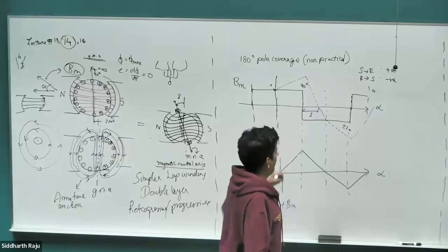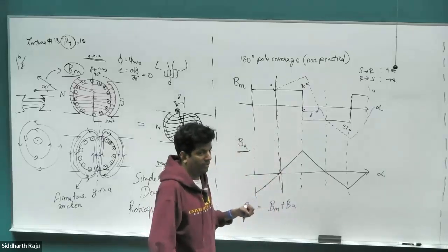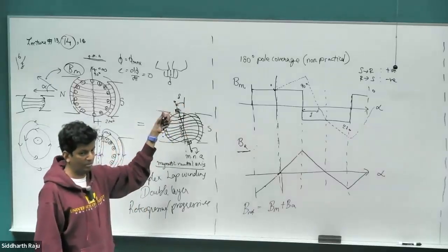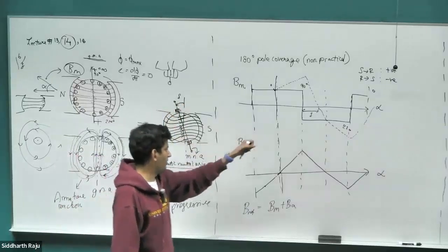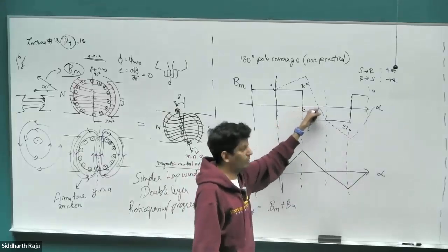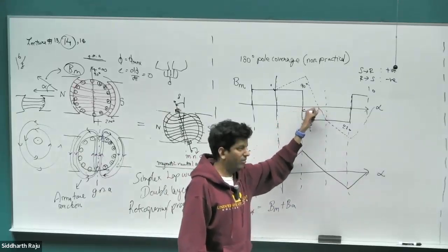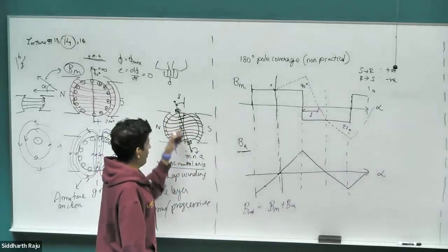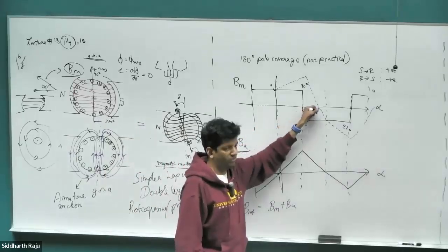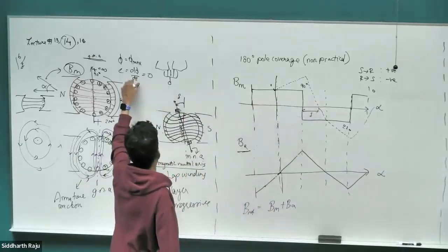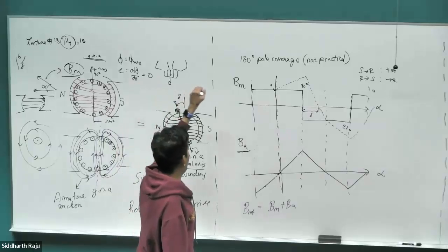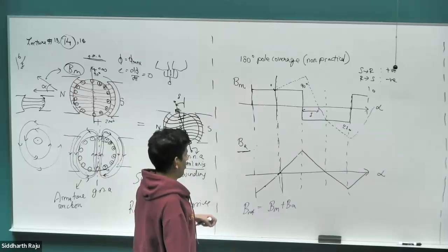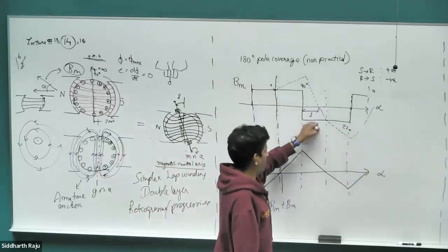in where the magnetic field in the air gap goes to 0. Right? Previously it was at 90 degrees, which is what we wanted it to be at because that's where the commutator initially was. But due to this armature reaction, that position where it goes to 0 gets shifted out. Okay? So our commutator position has to be shifted as well, so that the coil that's being shorted is the one where the flux is at maximum, but the d phi by dt would end up being minimum, so that the EMF across the coil goes to 0 when we make the short circuit. Right? So everybody clear on this point?